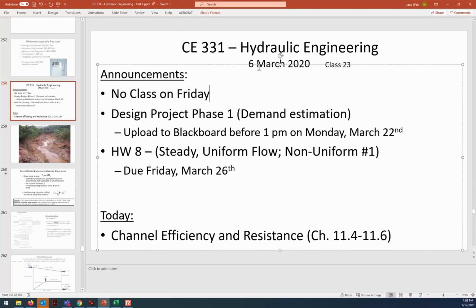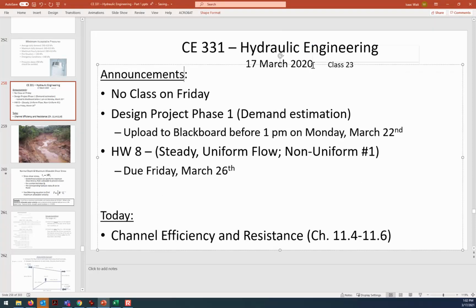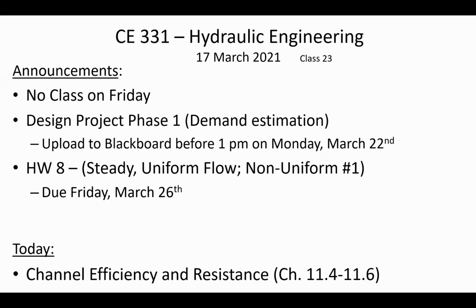Do specific research for the city that you've been assigned. For instance, if your assigned city is Phoenix, Arizona, then probably your demand estimation is going to be very different than somebody who lives in Columbus, Ohio, because of the availability of water and the pricing and the sorts of things that people do for landscaping.